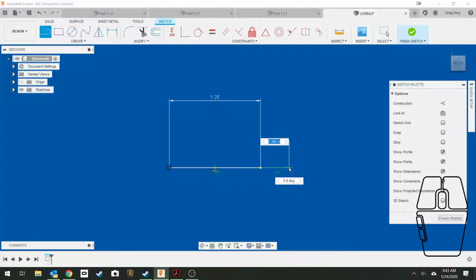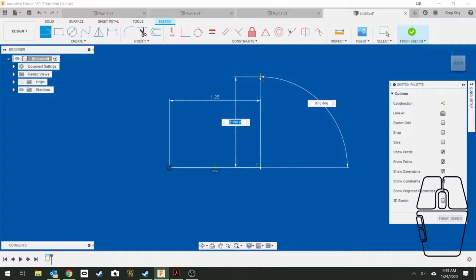What do I see now? What green hint do I see now? What's below my line? Parallel symbol. It's snapped and locked to be parallel. I come around like this intentionally so I can see that pop up and I can feel it. With my mouse, I can feel it snap in place there. It kind of jumps for me a little bit. I want it to be parallel. I want it to be perpendicular. I want that 90 degrees so I get that to pop up there. All right. I need 1, 2, 3, 4, 5, 6/4 today.